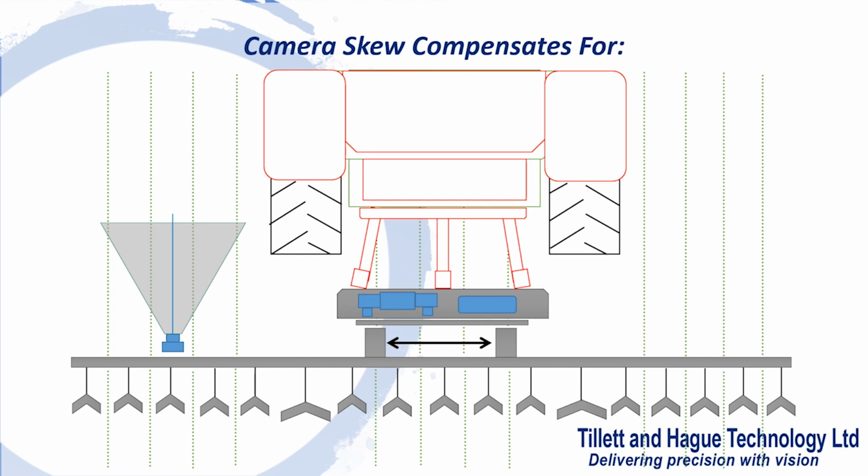It compensates for minor misalignment up to 3 degrees. It has been greatly exaggerated in this slide for illustration. It converges to a stable value after 100 meters of running. It is good practice to make this initial run-in in a flat field on crop with well-defined crop rows so that the value learned is as accurate as possible. Automatically learning camera alignment to high precision in this way increases acceptable mechanical tolerances without sacrificing tracking performance.